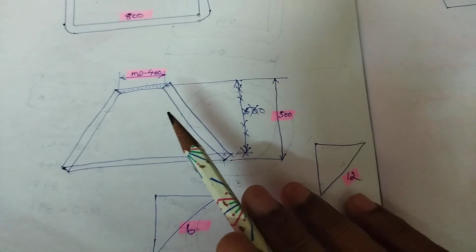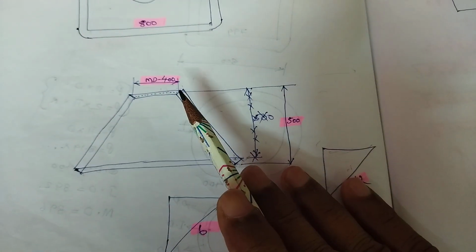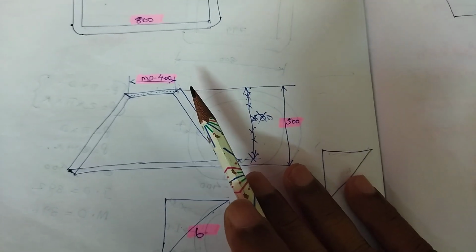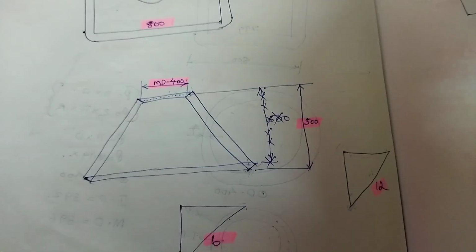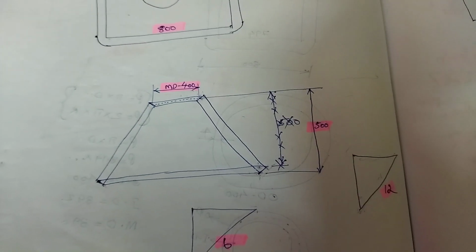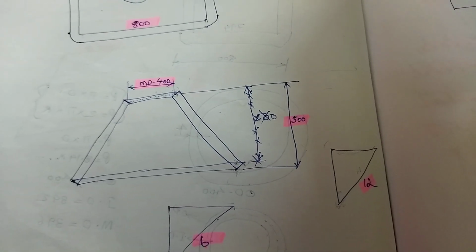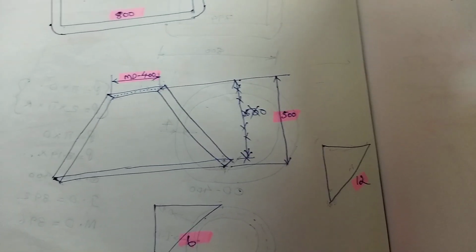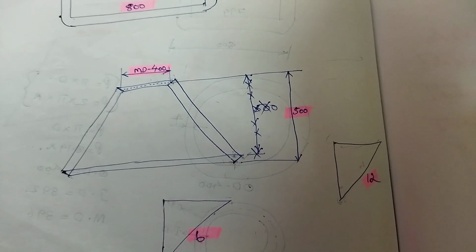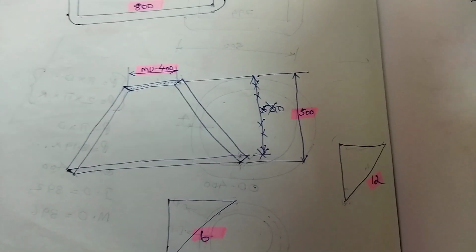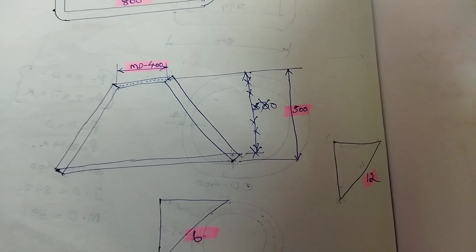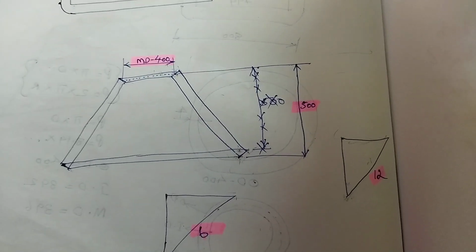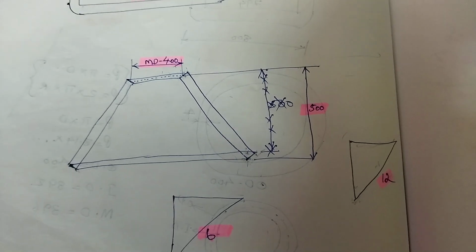We are going to make a square to round job, bottom side square and top side round. So when we take its development, one measurement we have to take. For making a round job, considering its perimeter, we use the medium perimeter, not the outer diameter, not the inner diameter. We use medium diameter and medium perimeter, like that.